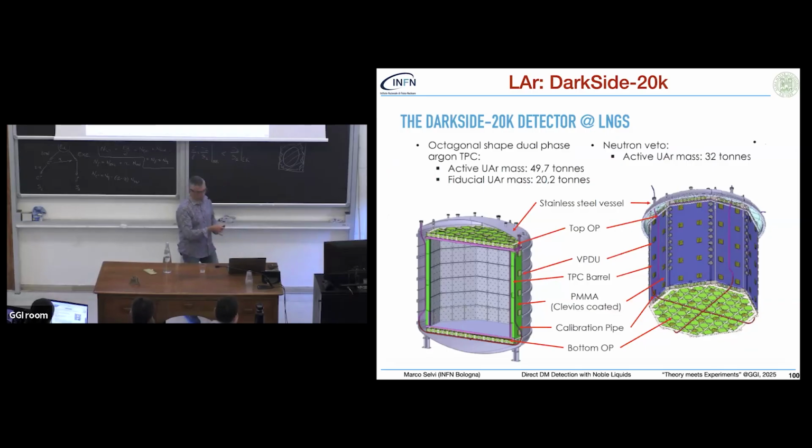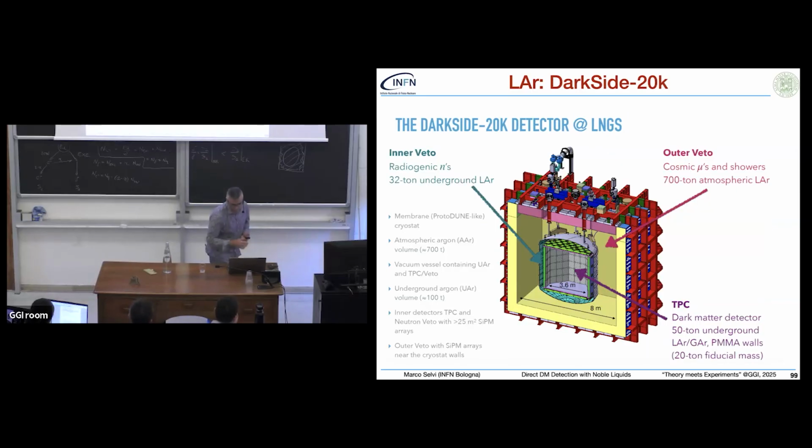This can be seen better here. So the TPC is quite large. It is 3.6 meters in size. That's challenging. It's made in acrylic, and this is also another challenge: the planarity. When you go to these very large dimensions, the planarity is an issue. The planarity has an effect on the electric field and so on. So everything has to be checked very carefully.